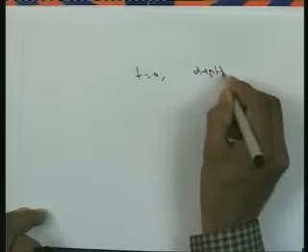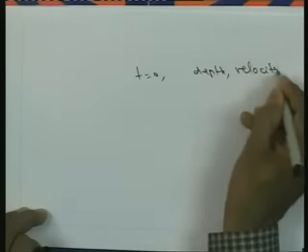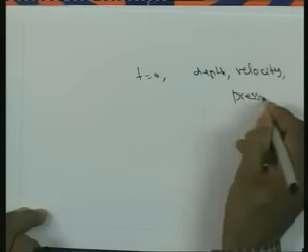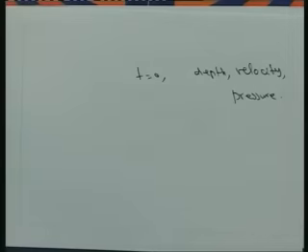Maybe the depth, velocity or pressure, how will these parameters be varying at time t equal to 0? From time t equal to 0, our transient analysis or unsteady state analysis of the fluid flow problem starts. So, these initial conditions are very much important in fluid flow analysis, and then the governing equations are prescribed. We have already prescribed the boundary conditions of the problem. So, with respect to this, the mathematical analysis is complete.